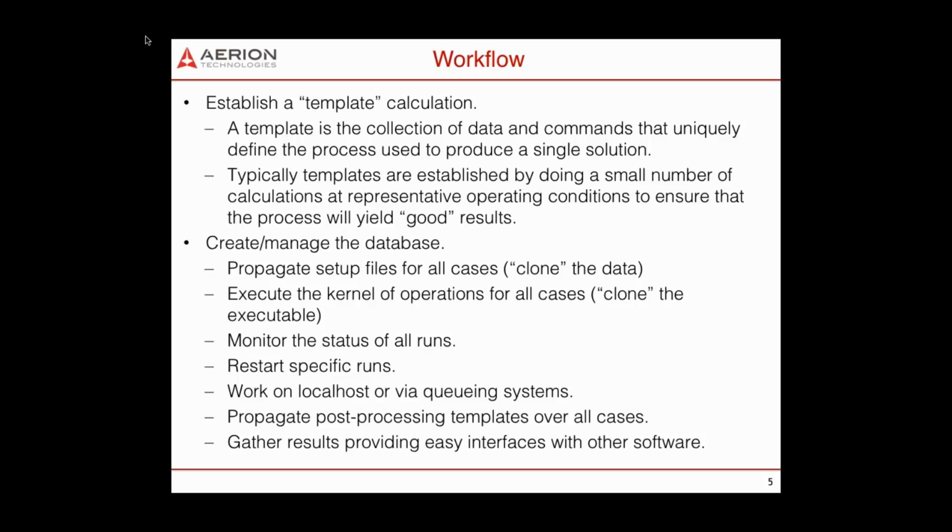To establish a template, what you're typically doing is subsampling the set of all operating conditions in the database, trying to find some representative operating conditions, and testing your theories about what options need to be present in the solver to ensure that the solver will yield a good result, not only at the representative operating conditions upon which you're testing, but also over the span of the database that is of interest.